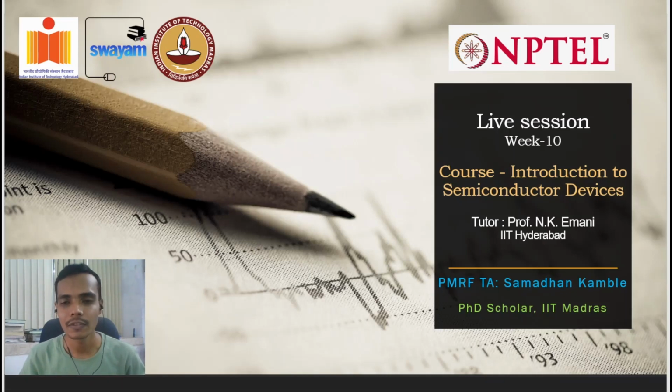In the last week, the week before this Monday, we studied the basics of the operation of a MOSFET, that is a metal oxide semiconductor field effect transistor, in which we looked at the saturation, the linear and the subthreshold regimes of operation, and then we also derived some of the basic expressions of the current as a function of the gate and the drain voltages.